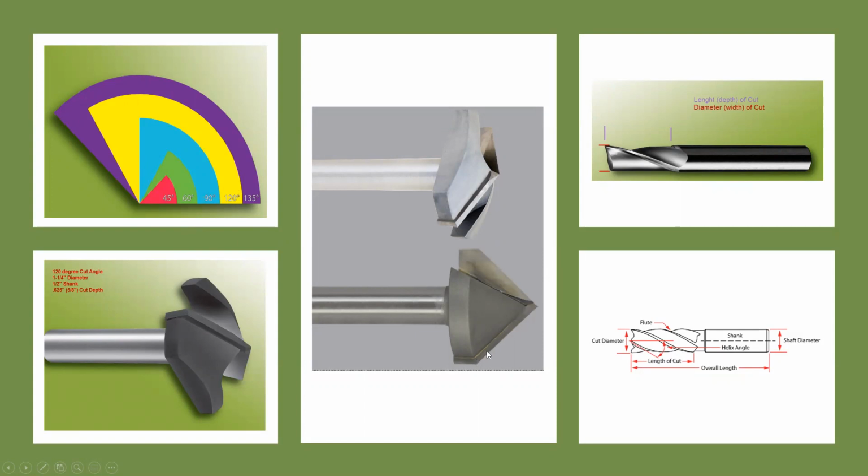So here we can see essentially a 90-degree cutter. And for the 90-degree cutter, as opposed to the 120-degree cutter that's at the top in the center image, the 90-degree cutter would need to go essentially 2 to 3 times the depth in the material to reveal the same carve width that the 120-degree cutter could utilize. So the 120-degree cutter could, for instance, use a ½ inch thick piece of material and reveal a wide carved letter that maybe had a line weight of ½ inch or 3/4 of an inch. In order to get 3/4 of an inch line width with the 90-degree cutter, the cutter would have to go much deeper into that material and potentially could cut through, for instance, 1/2 inch thick material. So the consideration is how wide do you want your line widths to be and how thick is the material going to be that you are working in.